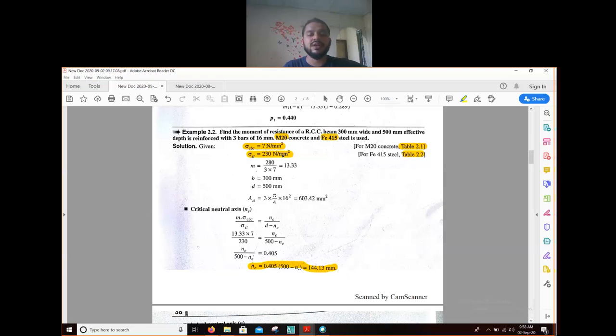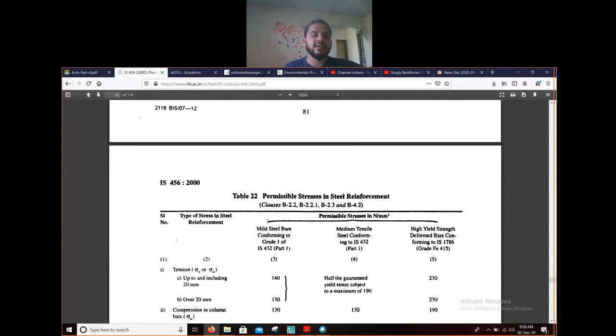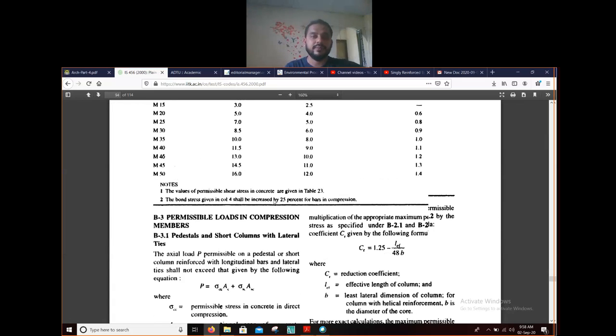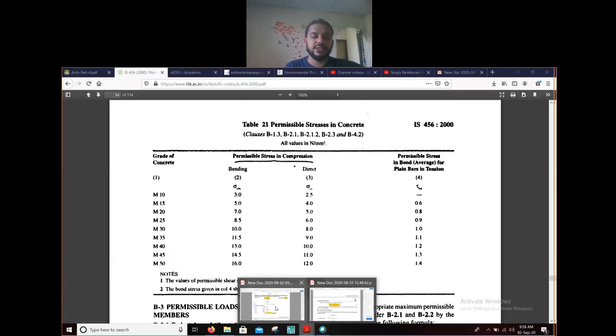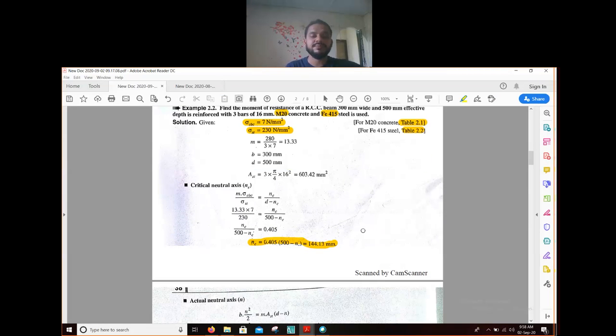Okay, and this value you will get from table number 22 of IS 456. From table number 22, you will get the value of sigma ST, and from table number 21 you will get the value of sigma CBC. Okay, so let us see the next problem. I hope all of you have understood this problem.